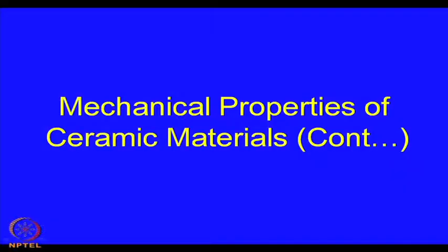We will continue our discussion on the mechanical properties of ceramic materials. In an earlier lecture, we introduced the concept of fracture toughness, the critical flaw size or crack size, and also the fracture stress, based on Griffith's theory, in which the total internal energy and the surface energy terms have been maximized.